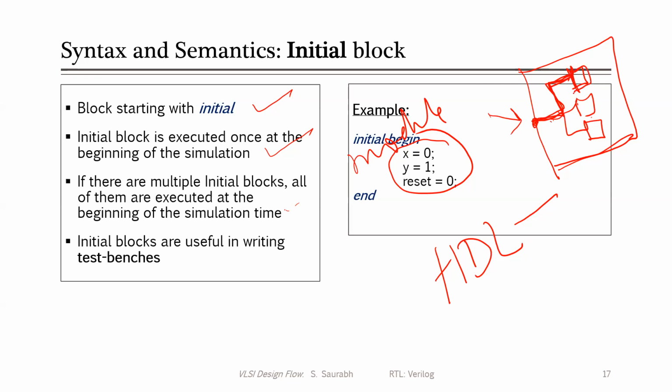But that behavior you cannot ensure. Why? Because of many reasons, and one of the foremost reasons is the process induced variation. Once you fabricate it, the behavior of this wire is not totally under your control, right? Therefore you cannot ensure where the signal will reach first in your layout, even if all of the wires are of the same length. Depending on the process induced variation, some block will be executing first and then the second one, and so on.